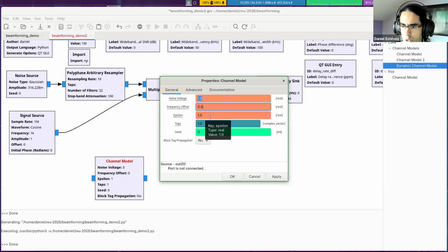For us, we are going to use it for something slightly different because this sampling frequency difference, the effect that it causes is a variable delay over time. It's a delay that increases over time. So when I said as the Earth is rotating, the delay that the antennas see will be changing continuously, that is the thing we are going to simulate with this epsilon.